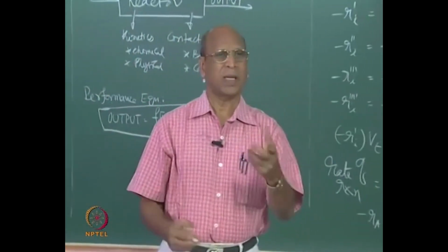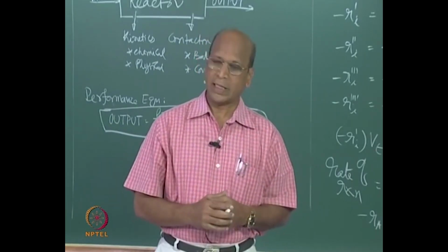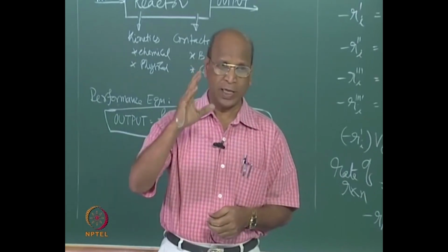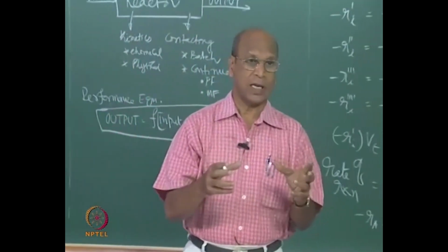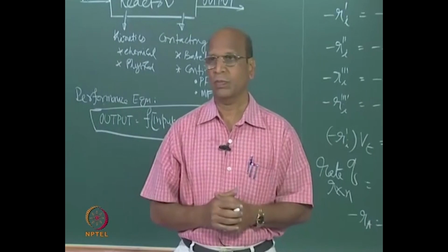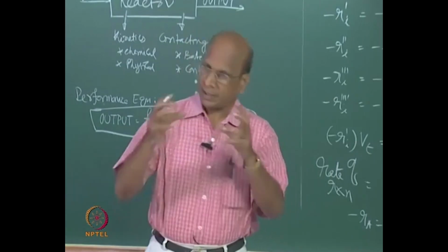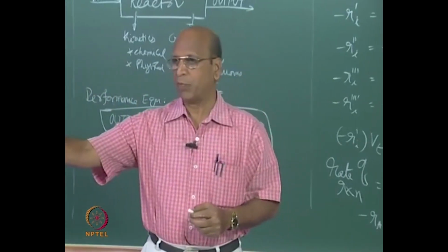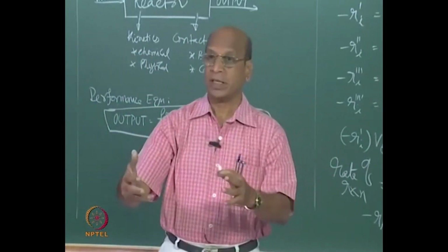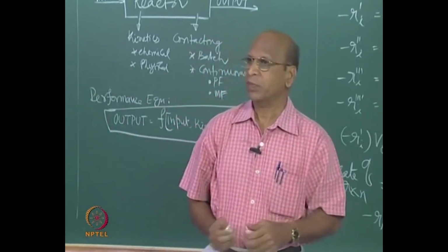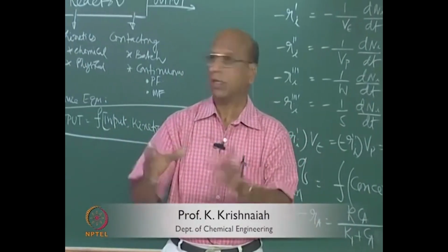But if I want to give numerical values for how large, I can tell you definitely 1000 tons per day, you will go for only continuous. But I have a problem to tell what to use for 10 tons or 50 tons. There economics and design will come into picture. You have to calculate separately for continuous and batch systems, compare the economics, and your labor and all that will come into picture, because in between someone has to discharge. You take all that criteria and then decide which side you are in.